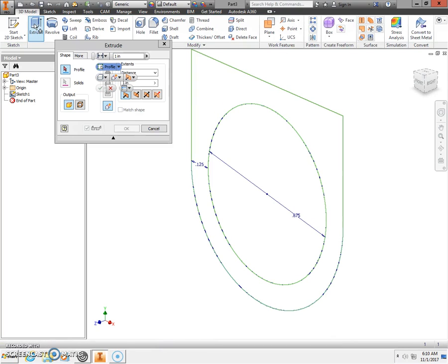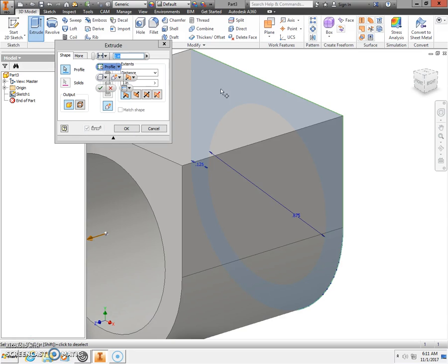So next we're going to click the green check mark, Finish Sketch, and we're going to extrude. If it does not automatically pick up your geometry, move your cursor to the ring, and click when that highlights pink, just like mine is. Make sure you're clicking the outside of the ring, not the inside where your finger goes. Then in our extrude menu, I want to extrude in direction 2, this button here.